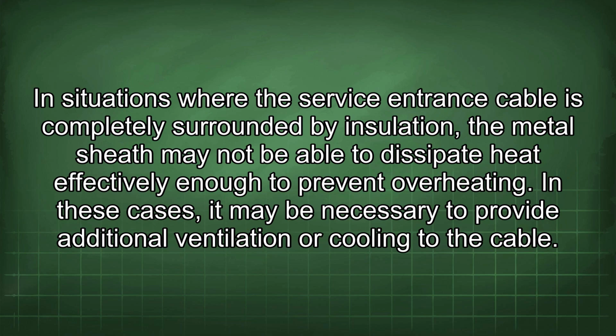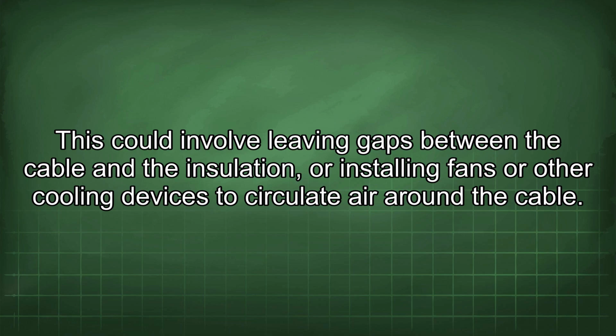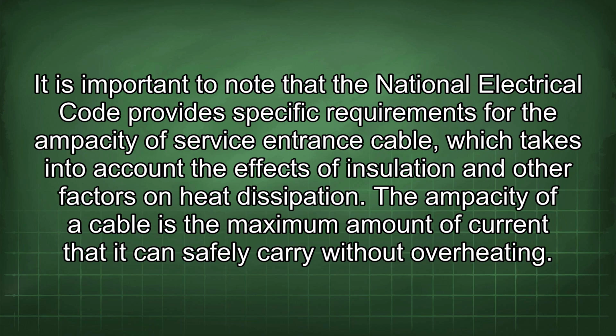In these cases, it may be necessary to provide additional ventilation or cooling to the cable. This could involve leaving gaps between the cable and the insulation, or installing fans or other cooling devices to circulate air around the cable. It is important to note that the National Electrical Code provides specific requirements for the ampacity of service entrance cable, which takes into account the effects of insulation and other factors on heat dissipation.